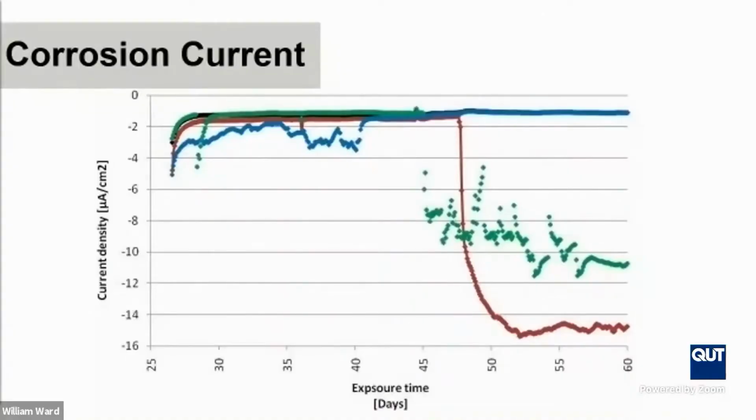So if we now start recording voltage and time rather than voltage and space, we can get a chart like the following. In this case, I'm showing current rather than voltage, and there's a distinctive increase as regions being monitored begin to corrode. So the red line shows corrosion activity beginning first at about the 46 days mark on an accelerated exposure, and then about the 45 days mark for the green, about the 48 days mark for the red line here. So essentially catching when corrosion begins electrically. So now we get it before physical damage is done. That's good.